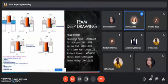Third, friction. Next, the rest of the blank starts to flow radially and to sink into the die pool. But the frictional force between the lower surface of the blank and upper flat surface of die tries to impede that flow. The magnitude of frictional force drops as the blank metal starts to move. Compression. Now, the blank undergoes compressive stresses. The width of the sector shrinks so that the larger perimeter of the blank can fit into the smaller perimeter of the die cavity.